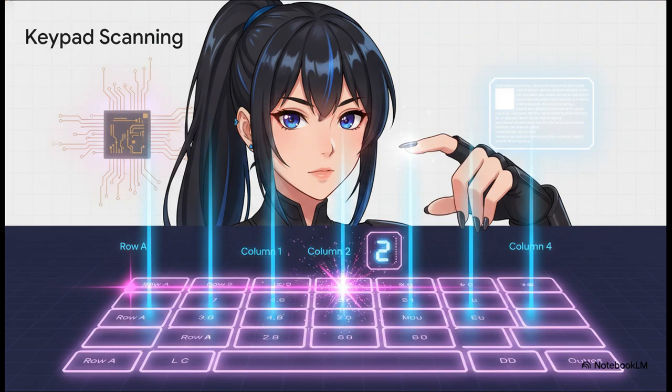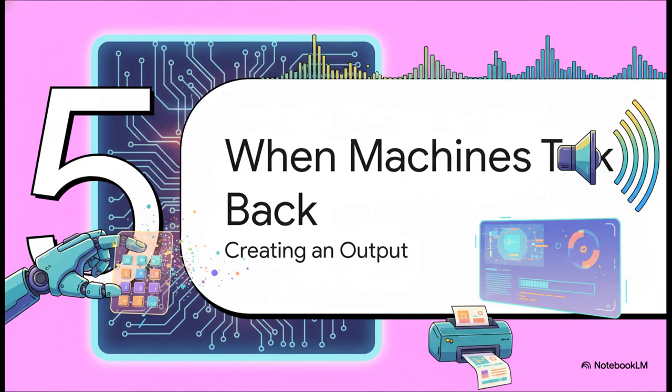First, it sends an active signal down just one row, let's say the top one. Then it immediately checks all 3 columns. Is it getting a signal back on any of them? If it gets a signal back on column 2 while row 1 is active, it knows you pressed the 2 key. If it doesn't find anything, it just shuts off that row, activates the next one down, and does the whole thing over again thousands of times a second. So the machine has listened. It's ignored the bounce, it's scanned the keypad, and it knows exactly what you want.